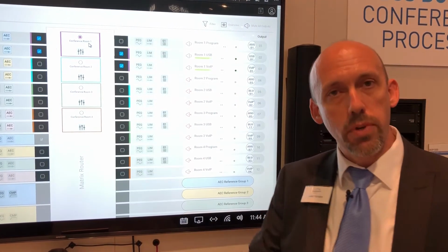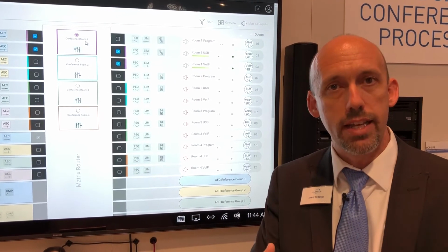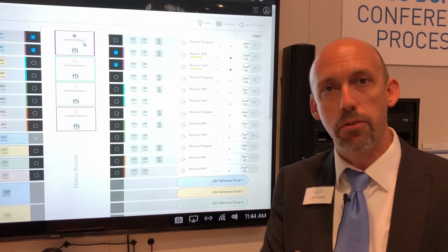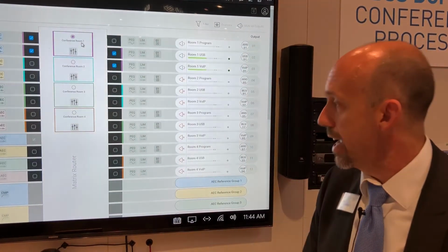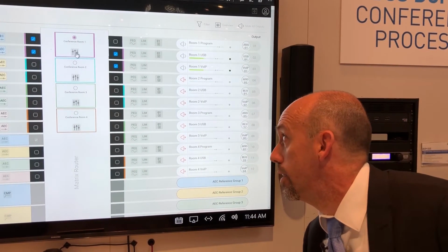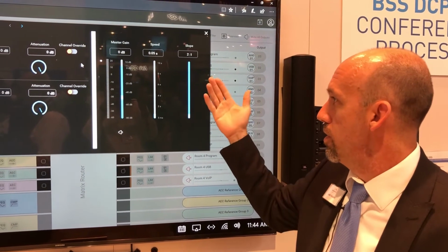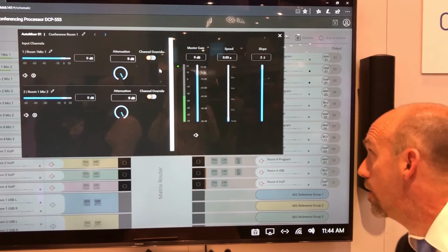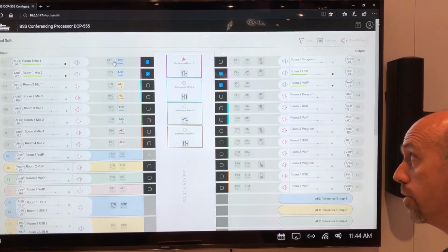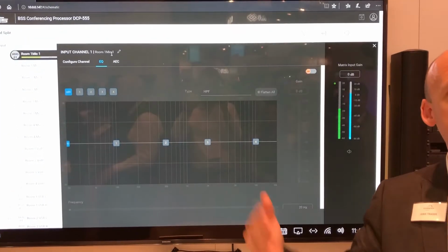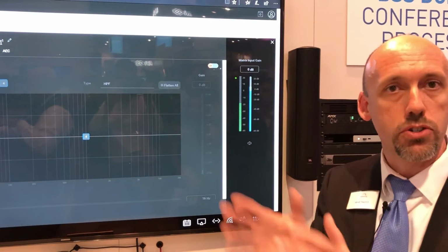The whole point of this was to really simplify the commissioning process. So we've already built all the DSP blocks and logic icons in there. Every icon in here is meaningful, meaning I can click on any icon and configure options on that. So in this case, maybe I just want to configure the specific gain levels and certain values for each independent mix, or I can go into individual inputs, individual outputs, and independently control that parametric EQ for that input, for that source, or for that destination.